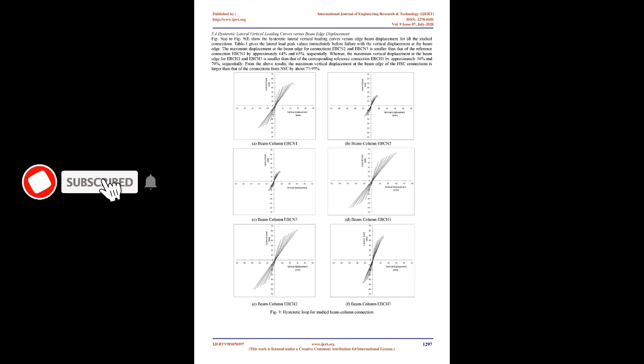Also, the results indicate that when using NSC, the effect of the distance between center lines of the beam and column on the ultimate failure load is clear, on the opposite side of when using HSC. Also, though the ACI 318-14 limits the eccentricity between the beam and the column center lines to 1/8 of column width, it has been found that the eccentricity of 15% of the column width is still on the safe side as predicted by the ACI 318-14 for HSC connections.